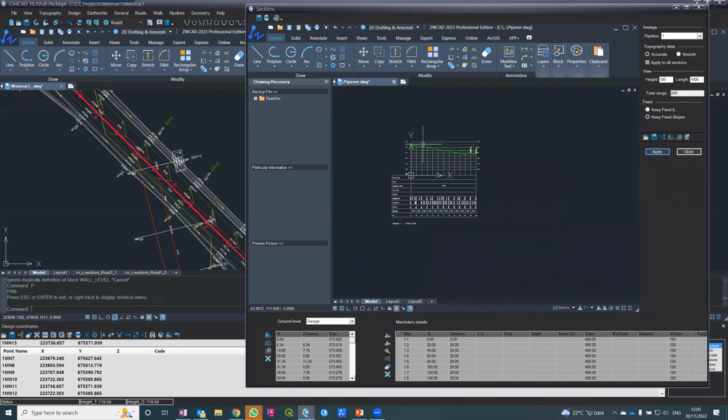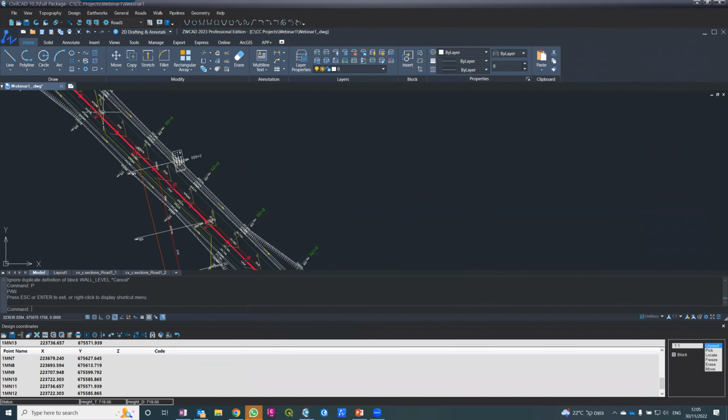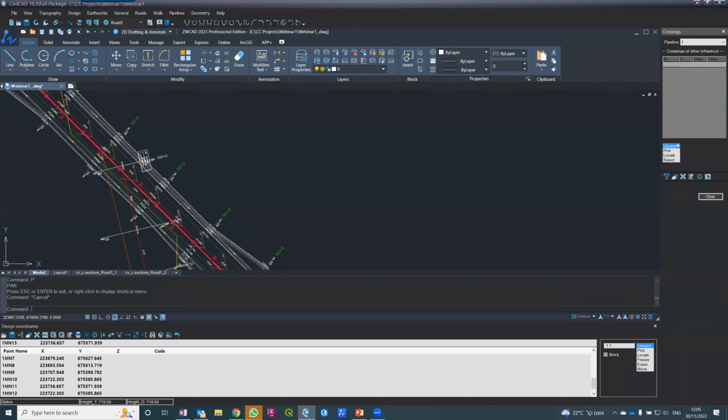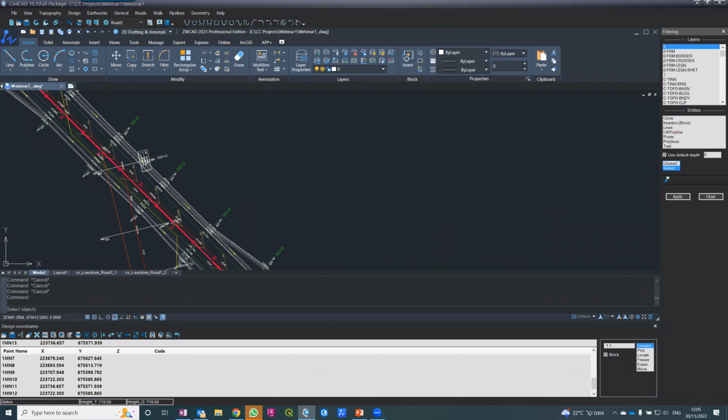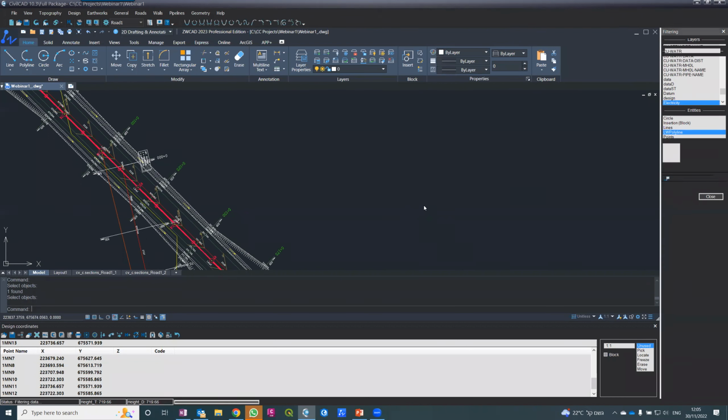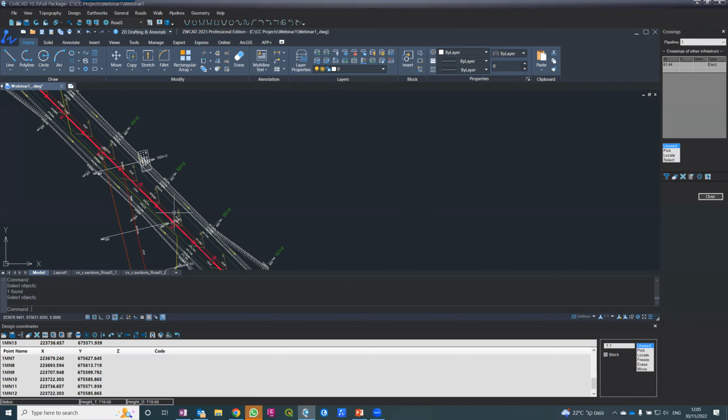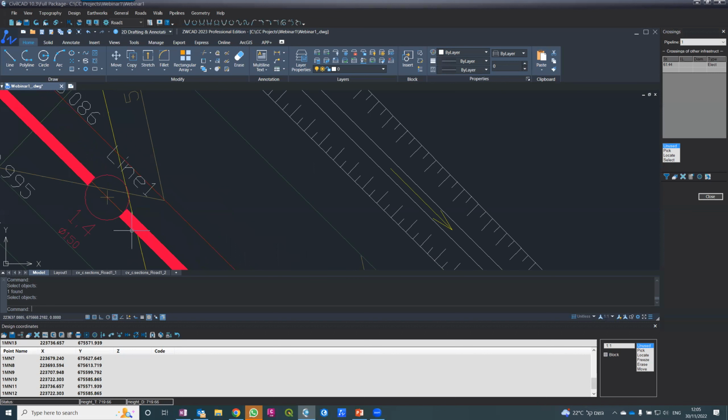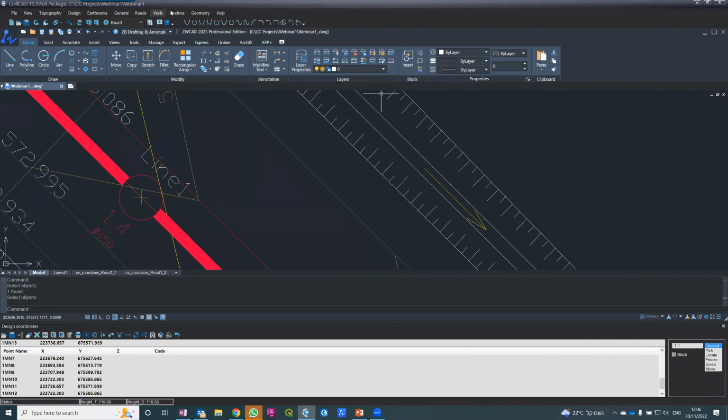The next thing that I intend to do is to project the electricity pipeline. So I'm going to pipeline crossings. I tell the software, again, use the same layer. We call it the electricity layer. And apply. So there's one intersection found after 61 meters. So this is the intersection with this electricity network, but there is no depth because the software doesn't know. So if I want, I can click here and tell the software, I know that the line is 1.2 meters and I know that the diameter is 10 cm. This is the data which I know.